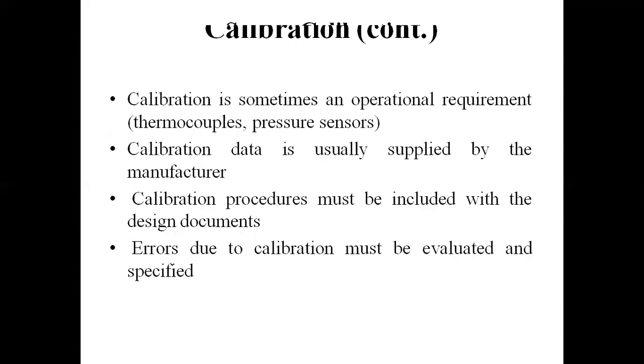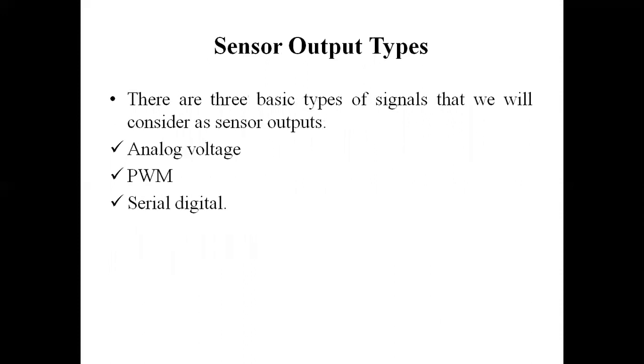Calibration is sometimes an operational requirement, for example in the case of a thermocouple or pressure sensor. Usually the calibration data is supplied by the manufacturers, and the procedures must be included with the design documents also. So errors due to calibration must be evaluated and specified.